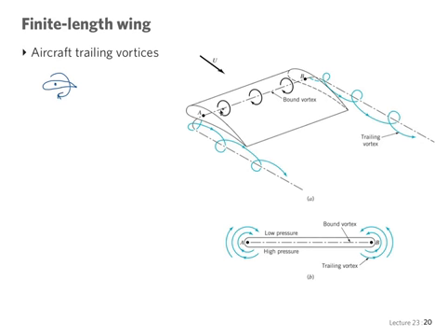Now if I look at the finite wing, you can imagine that that is actually called the bound vortex. And you can imagine that that bound vortex, once you get to the ends, it actually turns around like a horseshoe, and you have the vortex going all the way back in the wake, and you have this effect of the wingtip vortices.